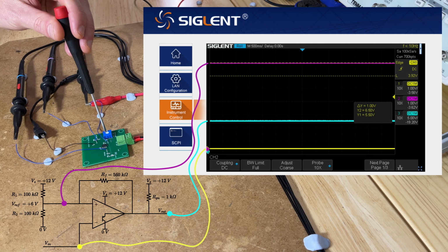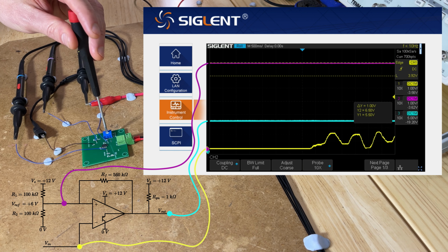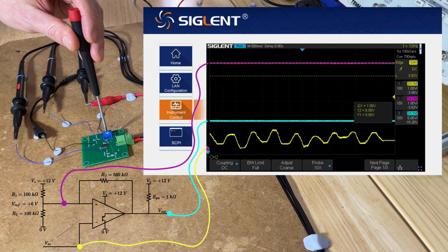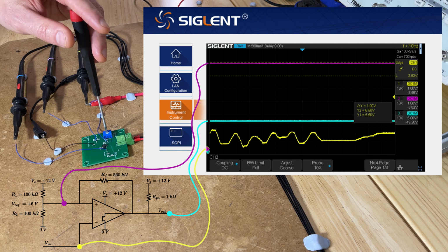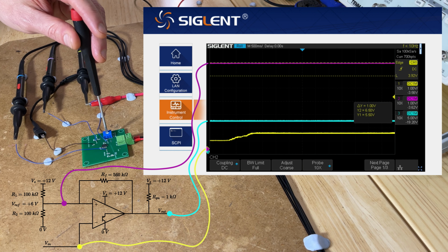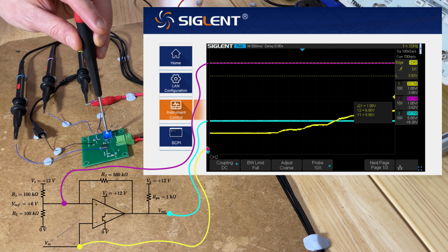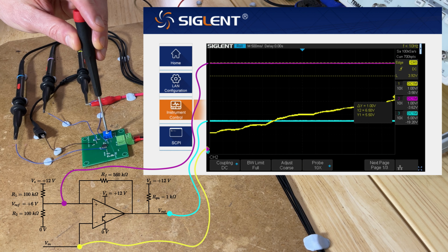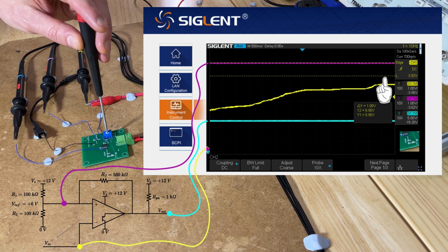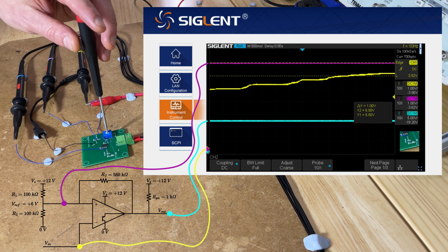So you can see right now, as I move my input, which is being fed in the inverting channel, we're well below the reference, so we can see that the output, the blue channel, is at logic high, so about 12 volts. So as I slowly raise the input, coming up to the lower hysteresis band of 5.5 volts, we'll notice nothing will happen to the output.